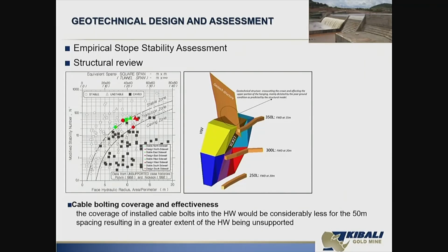stope stability chart. What that one was showing us is that as you increase the level spacing, your hydraulic radius becomes higher, and you end up pushing your stope into the transition and caving zone, compared to when you maintain it at, say, a smaller level spacing of 35 meters. That was a big one as well, because if you have your stope in the transition zone, that can be managed, but when you start falling into the caving zone, you can see that you have a bit of an issue.